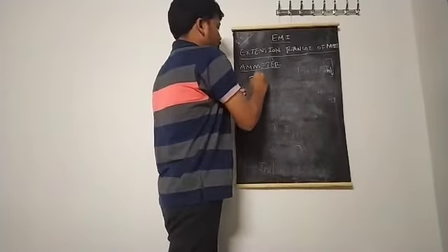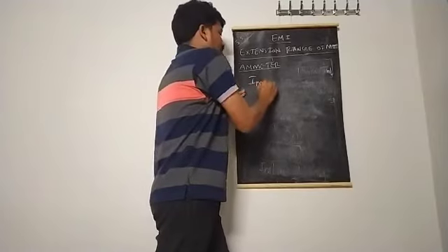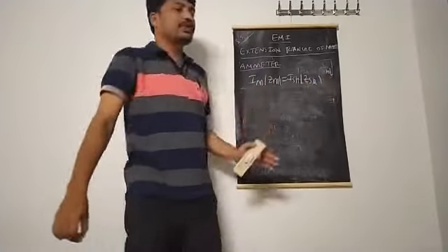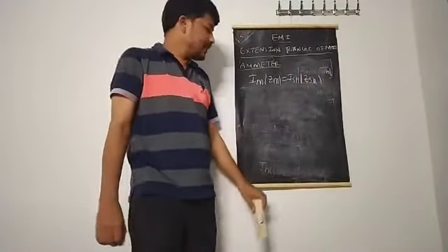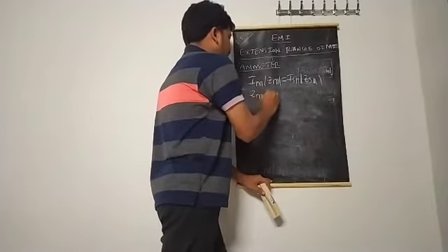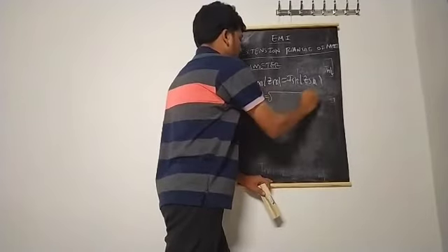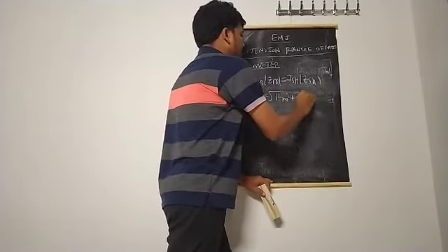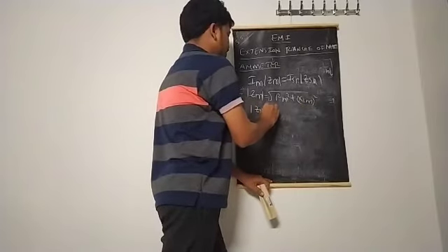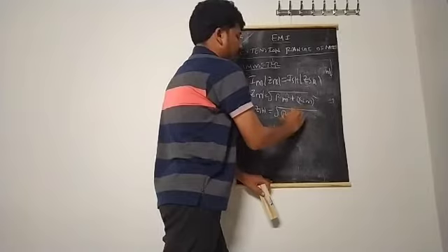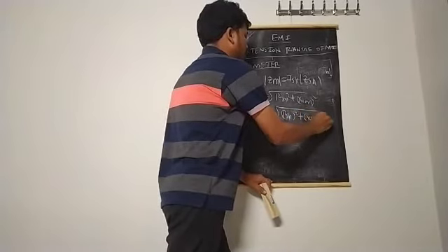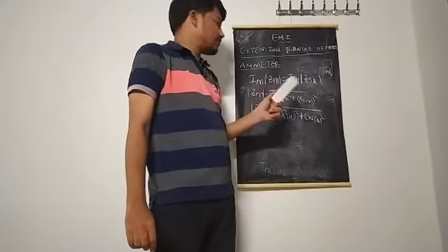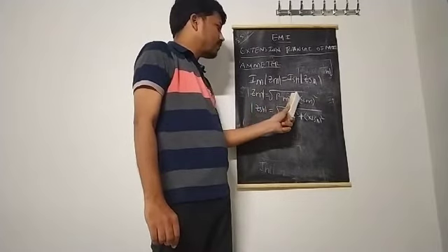So, from the equivalent circuit, we got this equation that is IM into ZM is equal to ISH into ZSH, where ZM is nothing but the meter impedance, that is the modulus of ZM is equal to square root of RM square plus XLM whole square. Similarly, ZSH is equal to square root of shunt resistance square plus XLSH whole square. Because Z is equal to R plus jX, therefore modulus of Z is square root of R square plus X square.